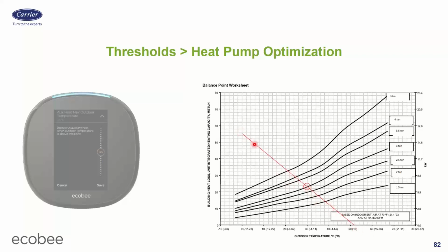As the outdoor temperature changes, my heating and cooling needs are going to change. Now, obviously, there are other factors in there, like, well, what if I came home and turned every light bulb on? Okay, we're not talking about that, dude. We're talking about when all the lights are off, nobody's home, it's dark, it's just sitting there trying to maintain 70 degrees, whatever. All right, that's what we're talking about. That's what I did my load calc based on.